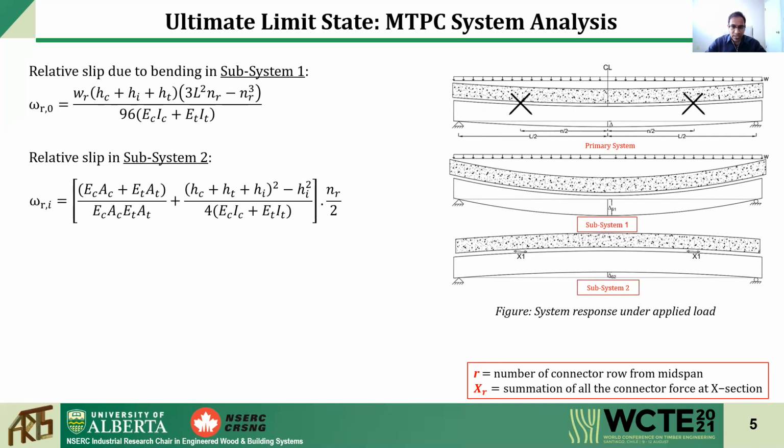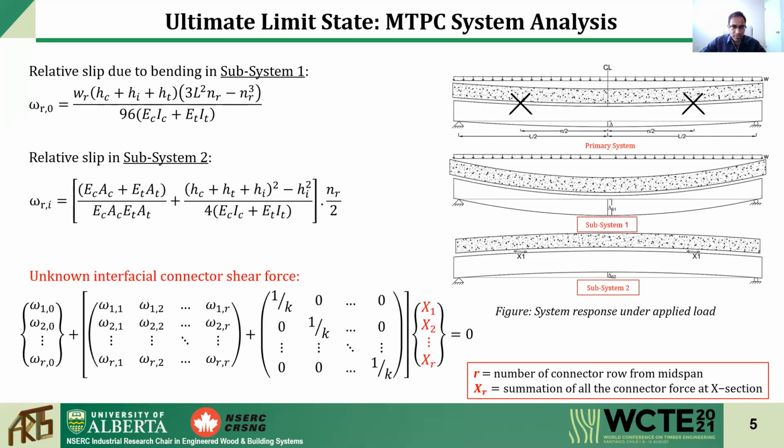Therefore, after applying the compatibility condition, we can calculate the unknown interfacial connector shear force. When we have more than one connector, this matrix can be solved and we can figure out the summation of all the connector forces in the X direction in the cross section.